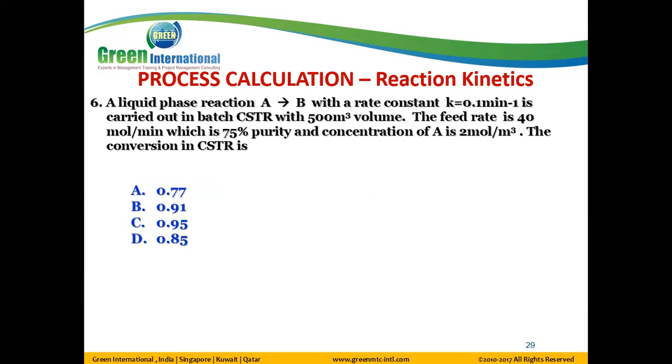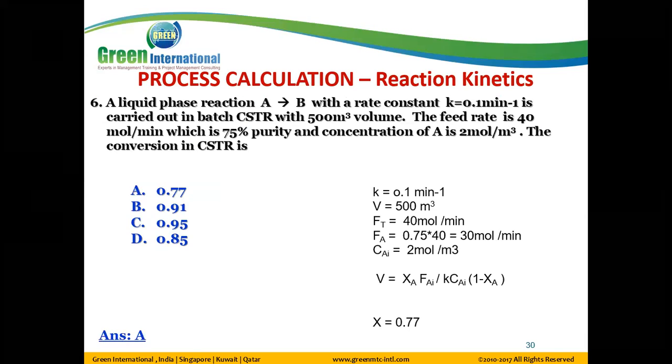They are asking the conversion. Even though the total is 40 mole, only 70% is pure, so FA0 is nothing but 30 mole per minute.